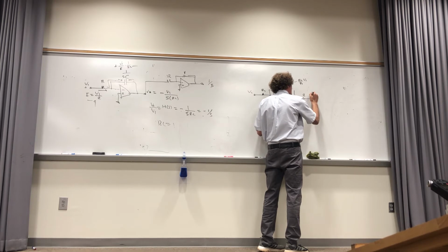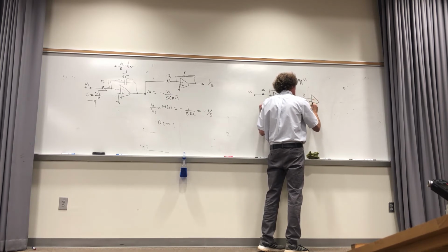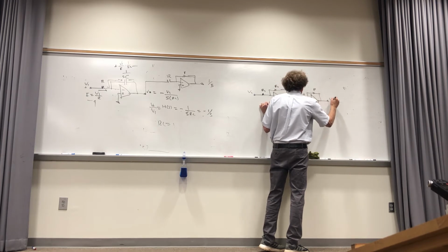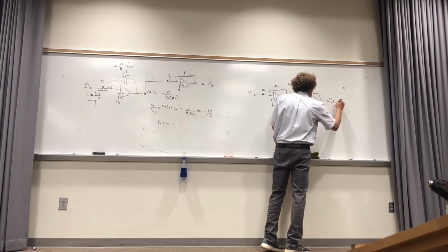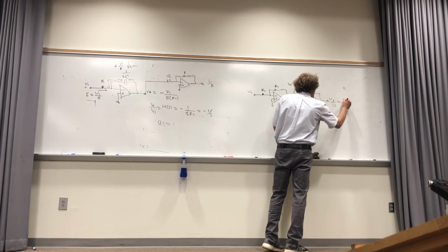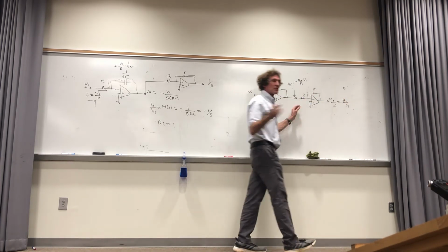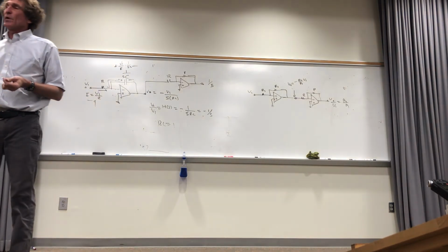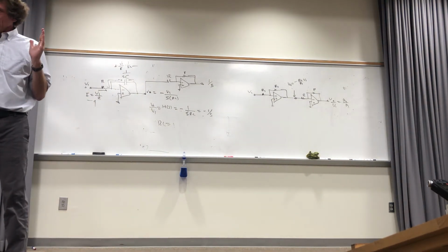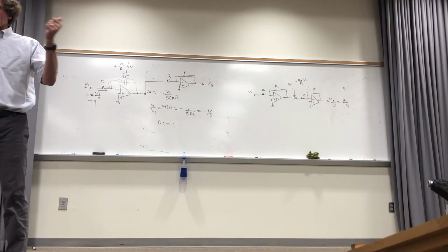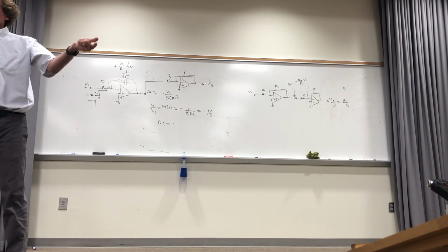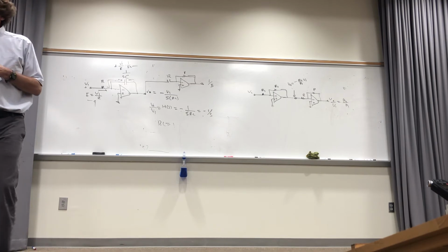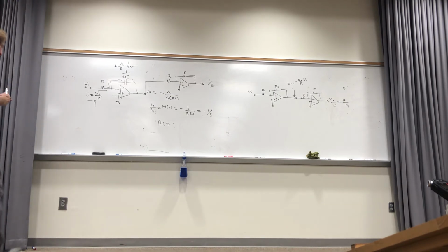The simple R here, negative, positive, grounded, another R here, and now my output over input for this circuit would just be R2 over R1, and you can make that 3, 5, 11, 100, whatever you want. Understand that? That's a simple way to get a gain block, a solid value. So now you've done summers, you have the 1 over S, and there's the simple gain blocks, and that's what makes up that.